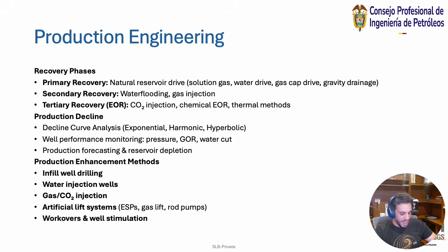So for example, let's say I have my 5 wells. It might be better for me, due to the nature of well 5, to change well 4, which is not producing as much, into a water injection well, and I will double or triple my production by injecting and helping well 5 out, right? Rather than just drilling a new well or an additional well. So water injection wells sometimes are existing wells that I convert from a producing well to an injecting well, or I drill a new well and I use it to inject water.